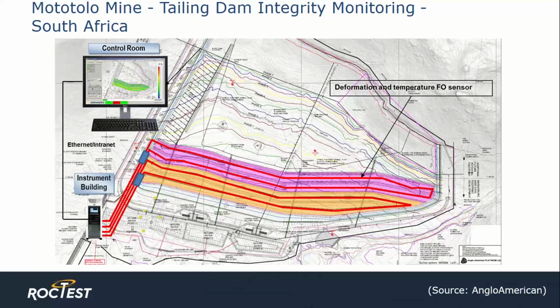Approximately 8 kilometers of Hydro&Geo sensing cable for strain and temperature monitoring were installed during dam construction. The cable was installed at the liner soil subgrade interface for strain monitoring in the liner and seepage detection due to liner defects. Monitoring was performed during the construction phase for quality assurance and later for structural integrity and leak detection during normal operations.